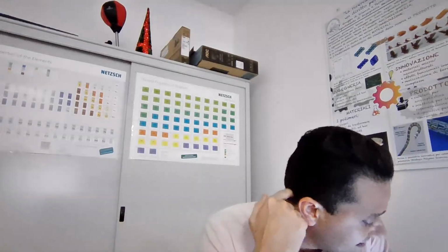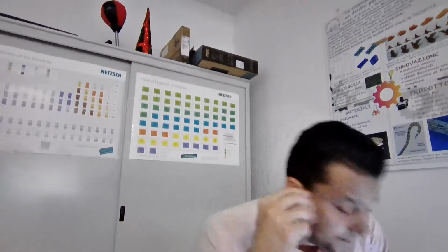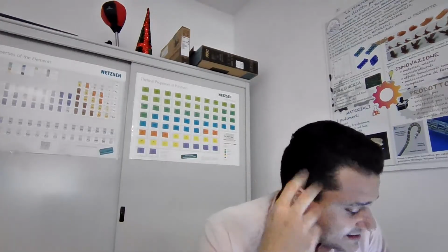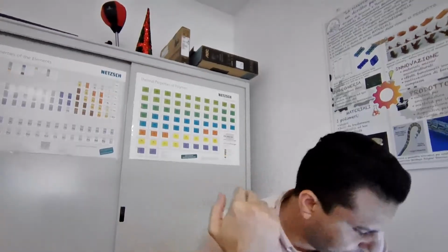When we have high local temperatures and high local stresses, which is common, it generates in the tread surface a thin layer, which I also mentioned in the previous video, typically of the order of a few micrometers. A surface layer of rubber with modified properties, usually named dead layer. It has a minimum contribution to the rubber friction, but it is there.